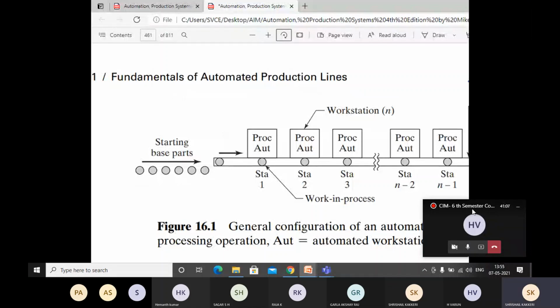For example, a very simple example, please look here. Try to give attention. This particular workstation has a time sequence of 1 minute. And this will be taking a time sequence of 2 minutes, for example. So that means the part processed in this workstation will take 1 minute, and the part processed in this workstation will take 2 minutes. So definitely the cycle rate or production rate will be double in this one, and it will be lesser, 0.5 times, in the other.